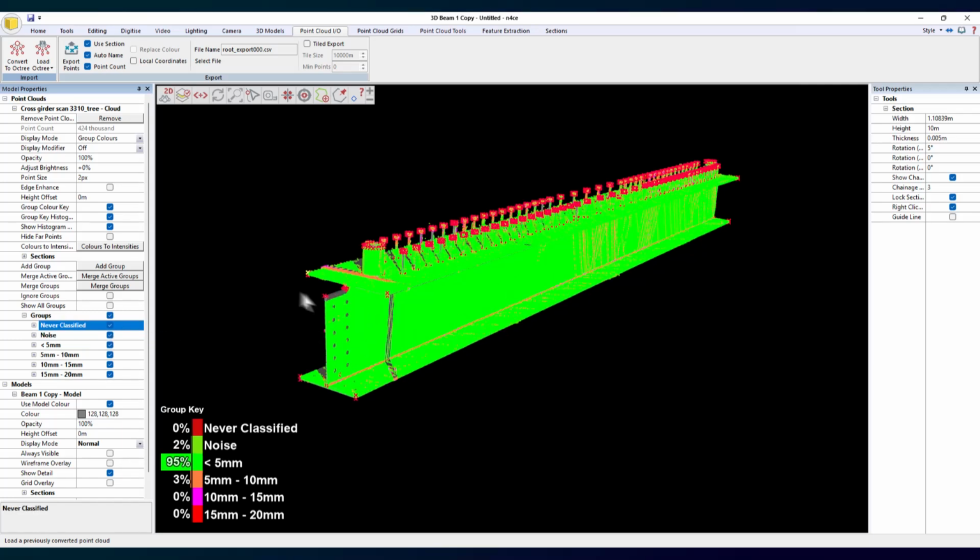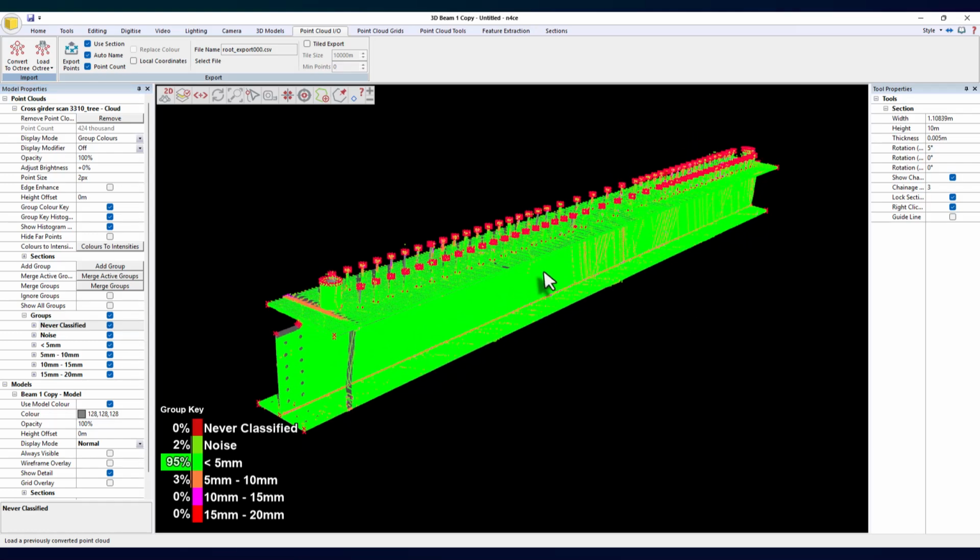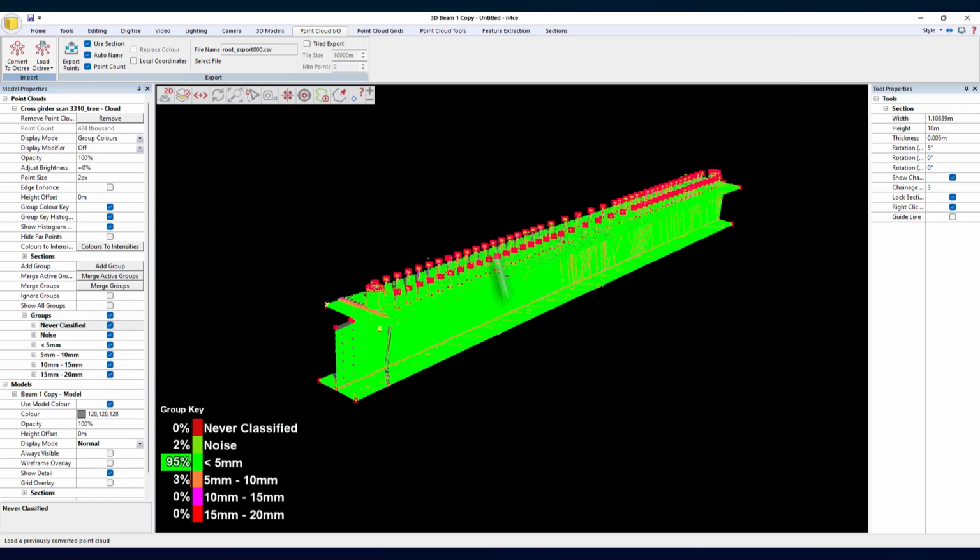So if you wanted to repeat this again, but doing it the other way around, you just merge your groups, which essentially gets rid of all of these and puts everything into the top group, and then just repeat the process. Okay. But in this situation, we've moved the model to where the scan is. So if you had lots of individual scans, i.e. in their own little groups or whatever, you can obviously accommodate lots of individual beams across a warehouse this way, rather than doing it the other way where we are moving the scan to the beam locations. And that concludes this little tutorial.